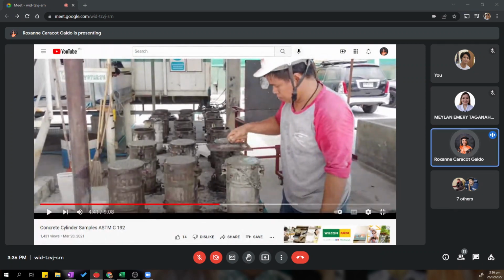Now after filling your cylinder mold, it is required as per the ASTM provision that you finish the top using a trowel, a trowel finish on the surface. Okay.